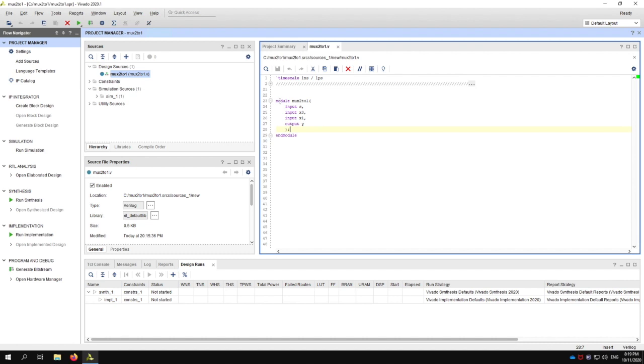Okay, so now let's look at the structure of a module. What did Vivado do with that information that I input into the create module window that we had earlier? For one thing, I have this keyword module, and then the name of the module that I gave to Vivado in that window. I called it Mux 2-to-1. Then inside these opening and ending parentheses, I have a comma separated list of my port names and the keywords input or output beside them.